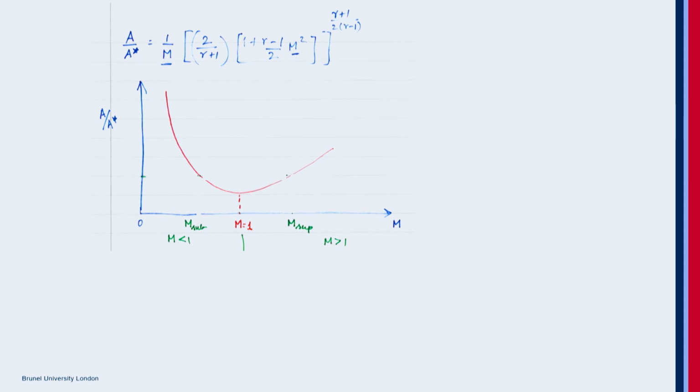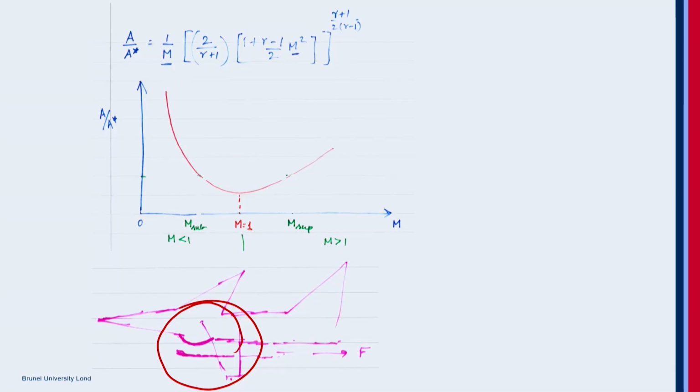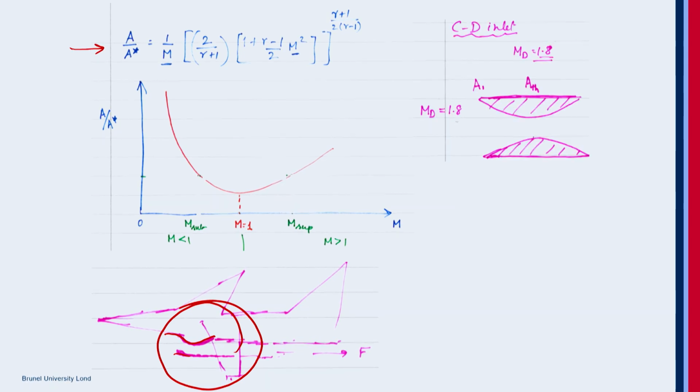So you're able to see that, yeah? So now you understand this one. So this is the aircraft inlet. If I want to design the inlet of this F-35 aircraft, if it is of convergent divergent geometry, then this isentropic solution plays a very important role, which says that for a design, I have chosen a design Mach number, somewhere here.